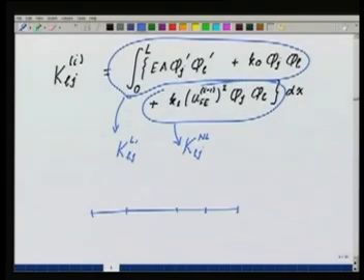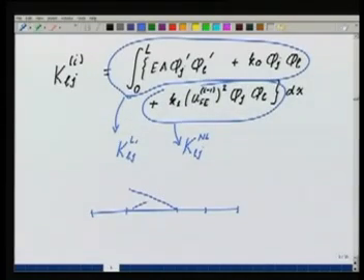Remember that now this will reduce to an element-wise integration procedure, because we are going to now write everything in terms of the element equations. So the global basis functions will reduce to element shape functions. So let us say I have these shape functions. Okay. So in the element, let us say I have nodes 1, 2, 3, 4, 5. This is my element 2. Okay. So this is now my global phi 2 and phi 3, and at the element level N1 of element 2, this is N2 of element 2.